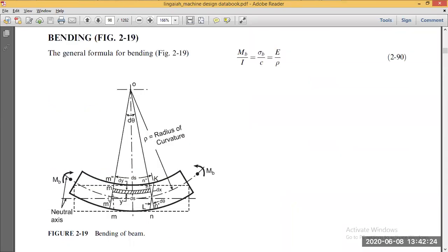All right, this is the one. You can see whenever bending moments are applied in both directions, the inner fiber is in compression and the outer one is in tension. The dotted one is the original shape. Once you apply the bending moment, you have compression and tension taking place.